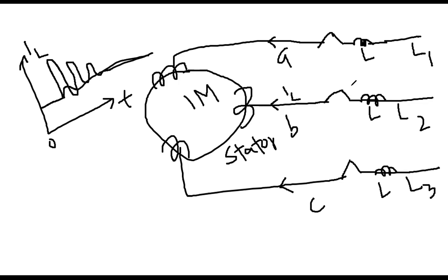So in the lab, actually you will be doing this, but you don't need to do anything. This is inbuilt. You will directly close the switch, so you are fully fine. In our laboratory, those induction motors have this property built in. It is the soft starting, so you will not face any problem. I am just explaining the phenomenon of what actually happens in real practice.